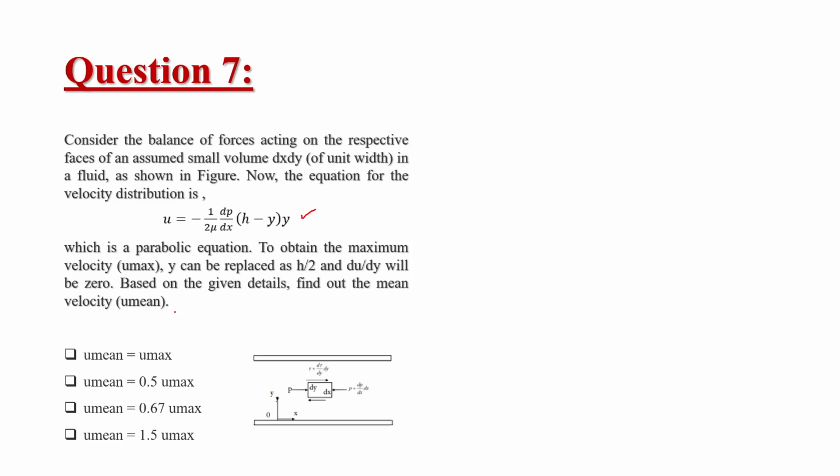If we expand this for a particular component, say for example the x component of velocity u, we will be having rho into dou u by dou t plus u into dou u by dou x plus v into dou u by dou y plus w into dou u by dou z.